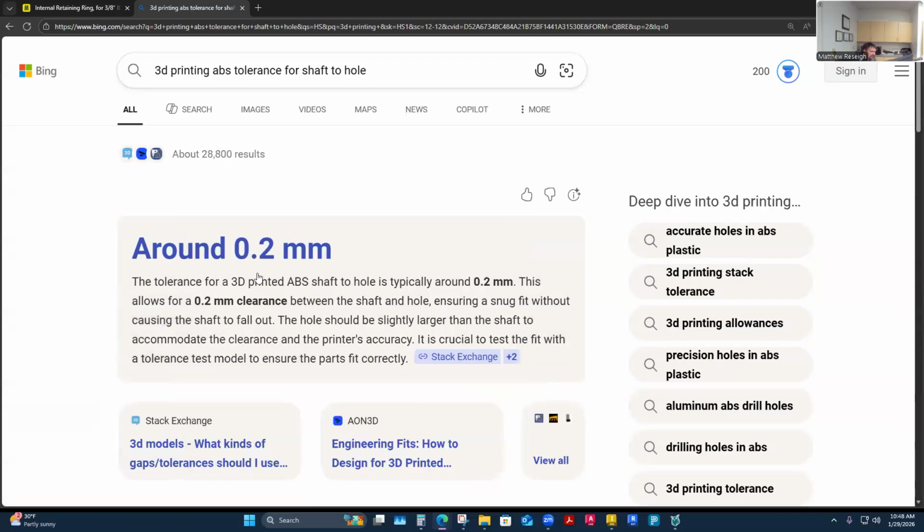It came up with 0.2 millimeters. It said maybe, and that's just a guess, because I think it's different from machine to machine. This is how you sometimes have to know your equipment to know how to work with your equipment. Our printer might print a little bit different than your home printer. It's kind of an experimental phase for a minute. It would be different if it was metal to metal versus plastic and 3D printed. I'd have to consider both, and what our real tolerance on metal is and what types of metal. It all plays a factor in what's going to fit.